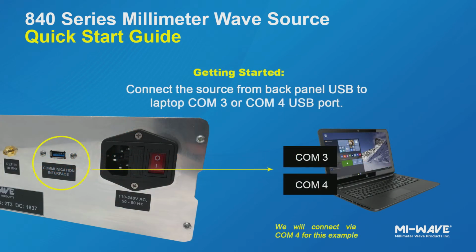Let's connect the back panel. Connect the source from the back panel USB to the laptop COM3 or COM4 USB port. For this example, we will be connecting via COM4.